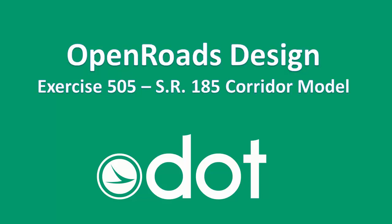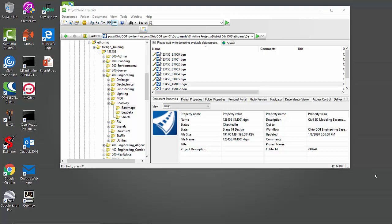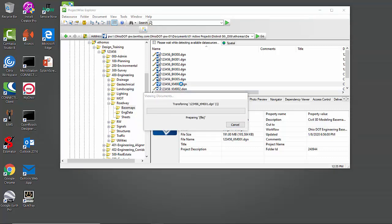This training video is for the Ohio DOT OpenRoads Designer Road Training, and this is for Section 505, our corridor modeling exercises, and this is the exercise for State Route 185 corridor. To get started, I have ProjectWise Explorer open, and I have my folder location open for my base maps, and I'm going to open the KM001 design file that was created in the previous video.